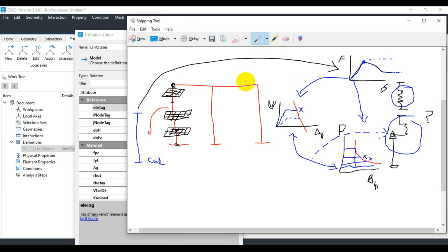So the thing is, by combining these models while describing different phenomena, the shear and the axial capacity that I discussed here, both models define a limit surface and they trigger a change in the hysteresis behavior that we may notice in our model if earthquake load is applied in this direction. So, how does it work here?